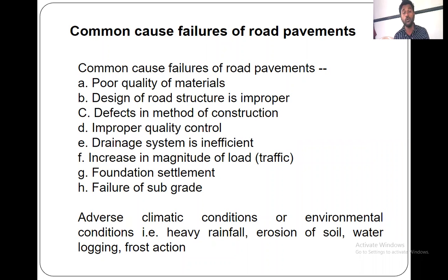Then next is the foundation settlement. Due to the low SBC, soil bearing capacity, what will happen? Suppose the load, whatever the traffic it is, is more, and the load carrying capacity of the soil is less, what will happen? The foundation will get settled, and due to this settlement of the foundation, cracks will develop on the pavements, and the subgrade layer and subbase layer will fail.